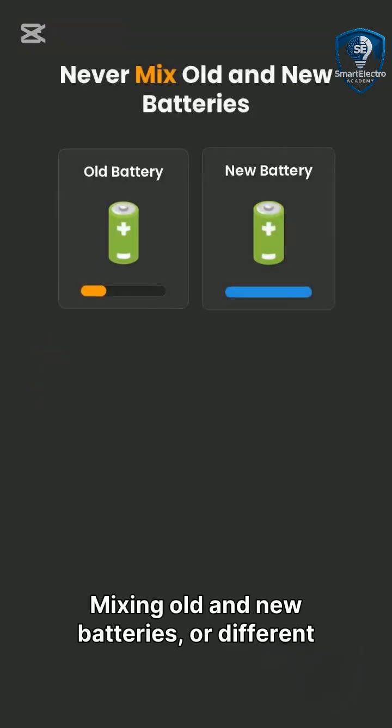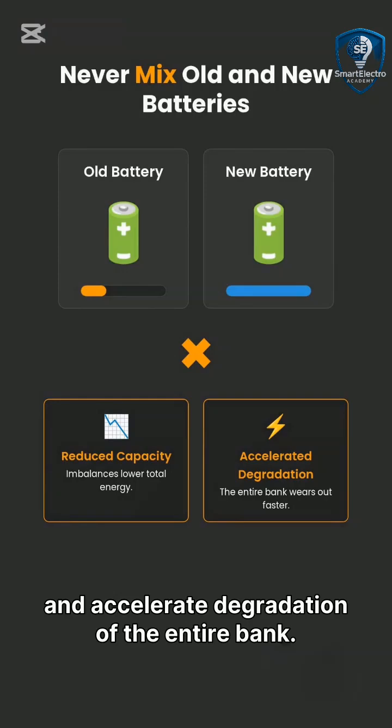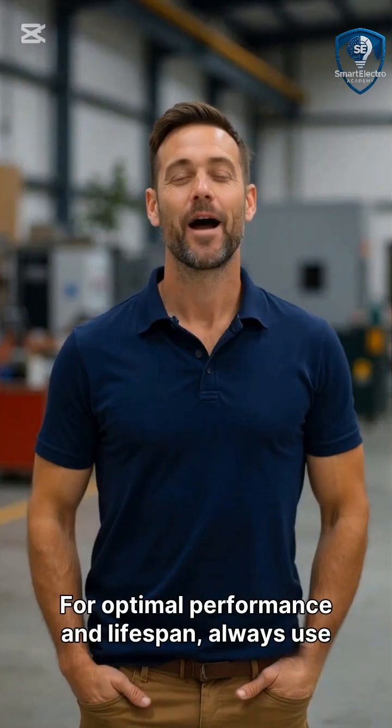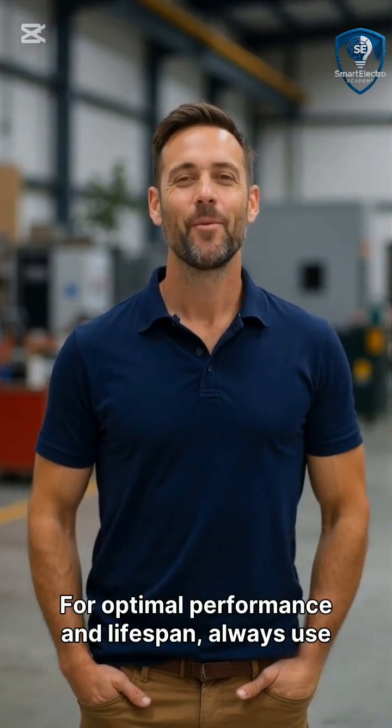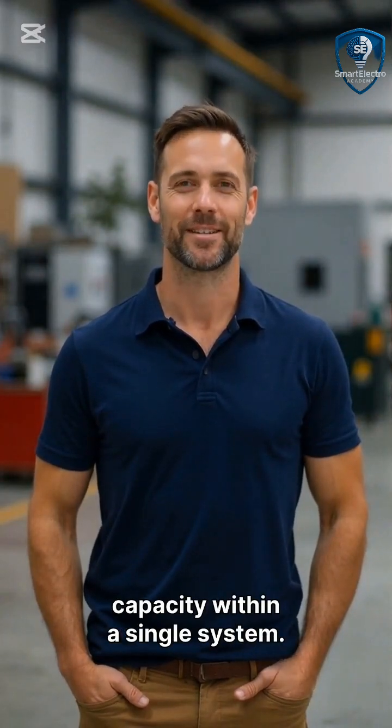Mixing old and new batteries, or different types, creates imbalances that reduce overall capacity and accelerate degradation of the entire bank. For optimal performance and lifespan, always use batteries of the same age, type, and capacity within a single system.